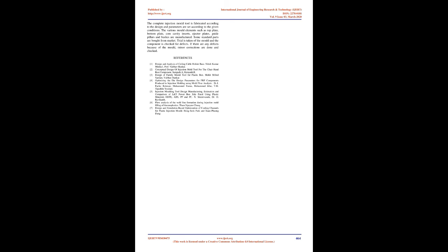Conclusion. In this paper, tool design and analysis for 10-position drawer housing connector is done in NX 11.0 software. The complete injection mold tool is fabricated according to the design and parameters are set according to the given conditions. The various mold elements such as top plate, bottom plate, core cavity inserts, ejector plates, guide pillars, and bushes are manufactured. Some standard parts are bought from market. Trial is taken of the mold and the component is checked for defects. If there are any defects because of the mold, minor corrections are done and checked.